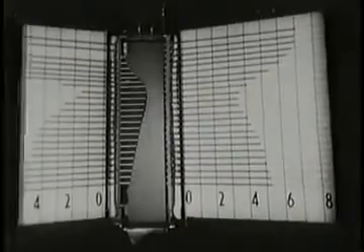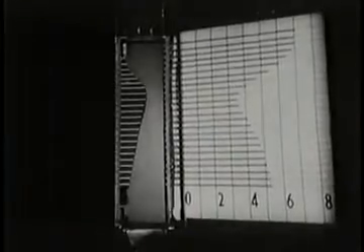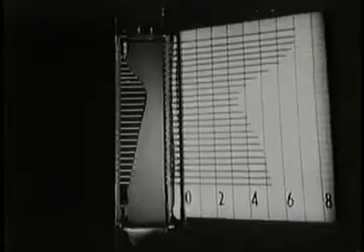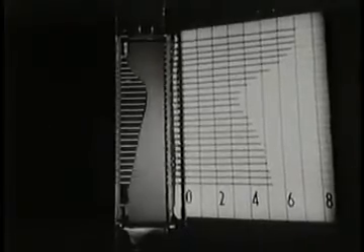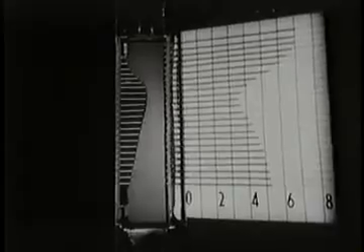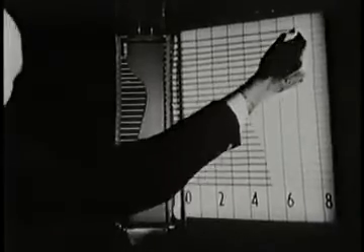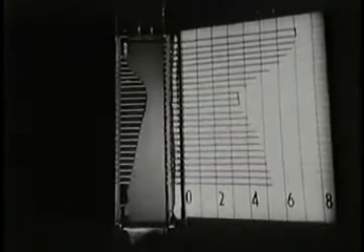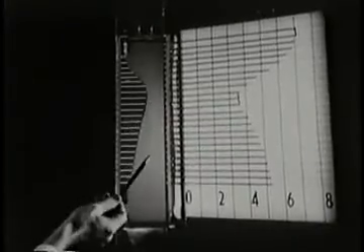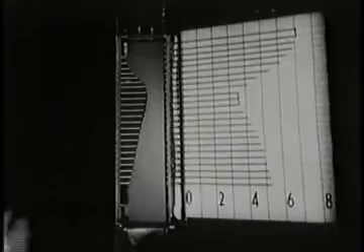Continuity tells us that because of the area contraction, the velocity increases to the throat, and this causes a pressure drop. Downstream of the throat, the area increase produces a velocity decrease, and this causes the pressure to rise.